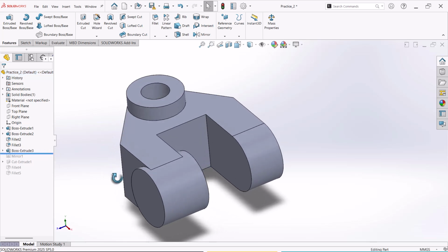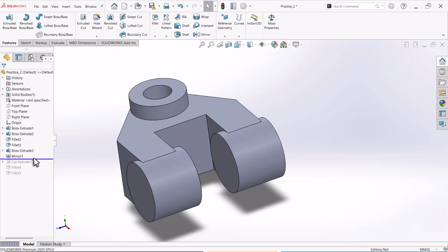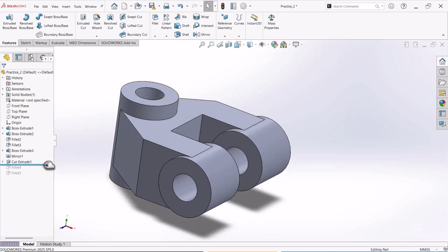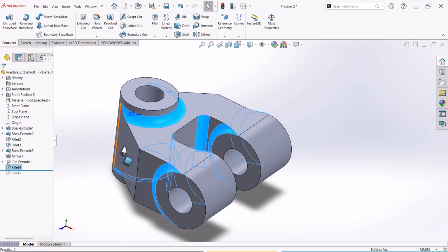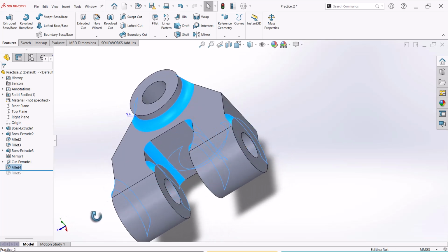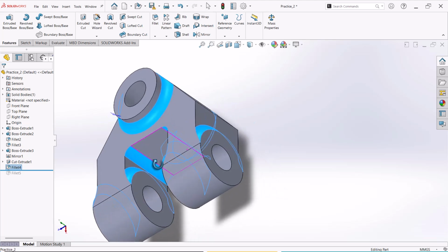Then we are going to extrude the cylinder by keeping 3 mm distance over here and this much blind depth. Then we are going to mirror that part, and we'll have a center cut like this, and we're going to have a fillet 4, which is of value, let's say 4 over here on the bottom side, these two cylinders and the corner sides.